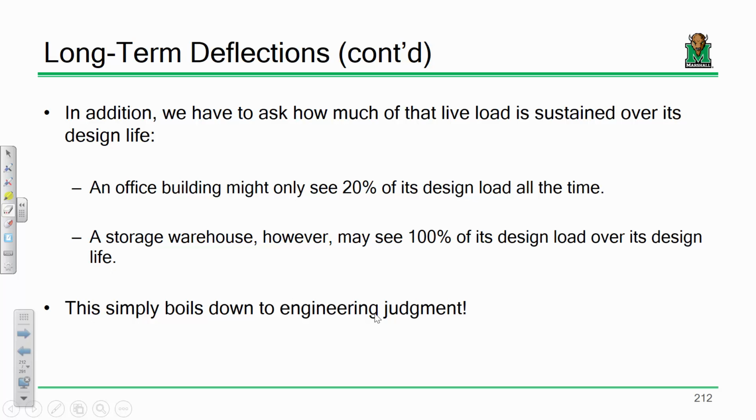One question that we have to ask, and I know students sometimes get a little frustrated at the final answer, is how much live load is sustained over an element's design life. And a really nice example of that is looking at this classroom. When we first started discussing loads in this class, we agreed that the load in here is different than, say, the load in a warehouse or a library. Remember how we said the library load is about 150 pounds per square foot? That's because there's book stacks all over the place, and they are very, very heavy, right? Well, that's absolutely the case.